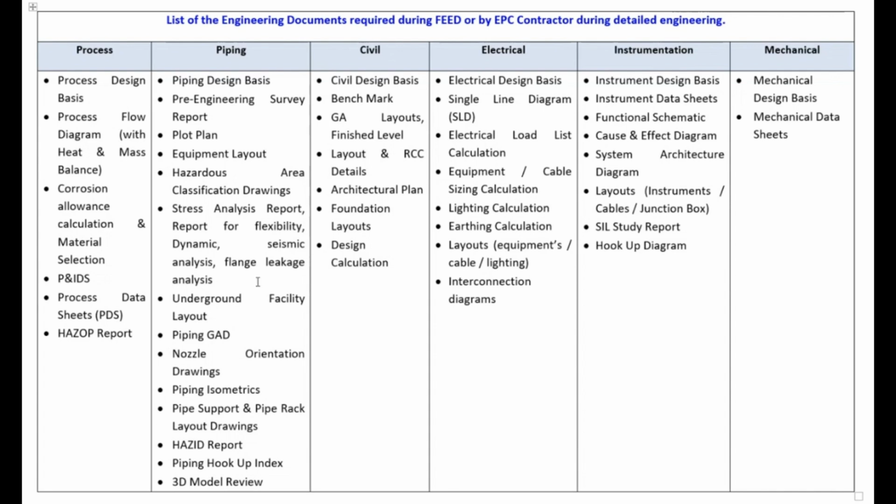And in this also, when we are analyzing the observations about rotary equipment, air compressor, gas compressor, and pumps also, in that scenario one more load is considered, which is called the seismic load. When the pipe is put on the pipe rack, hanging, and suppose the compressor is running, suddenly an earthquake comes, it will add extra stress on the compressor, the pipe joint, and the pipe, correct? In that scenario also, the seismic analysis will tell you it is good to go.